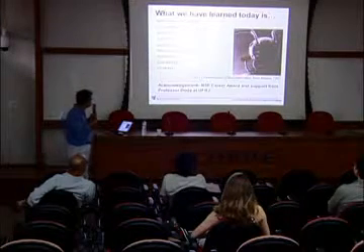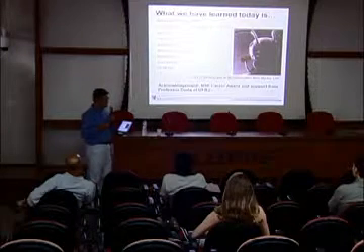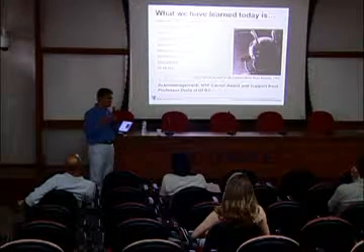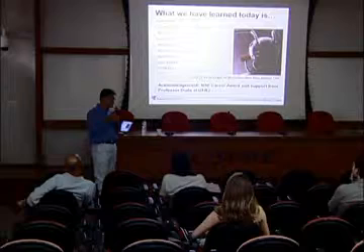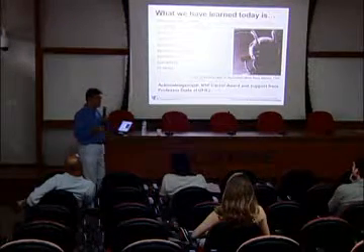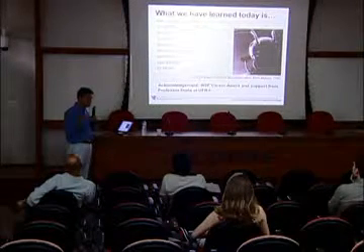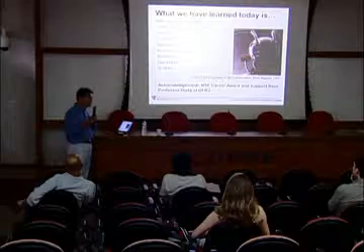And in the MEMS processes, we discussed lithography, UV lithography, and then deposition, physical vapor deposition and chemical vapor deposition. And also we discussed etching methods using gas phase or wet etching.